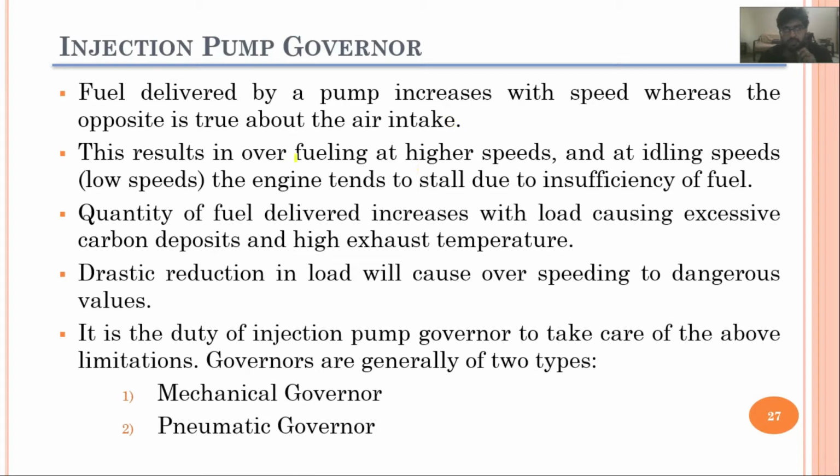At idling speeds, the engine tends to stall due to insufficiency of fuel. Similarly, at higher speeds we have the problem of overfueling, but at lower speeds the engine may stall because a smaller amount of fuel is being injected.